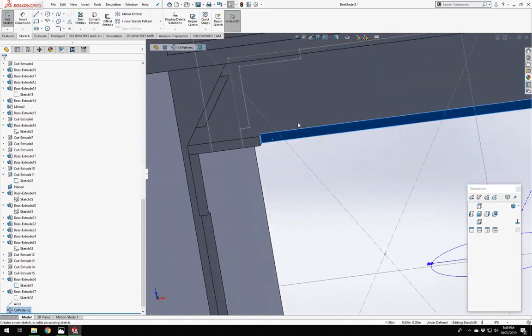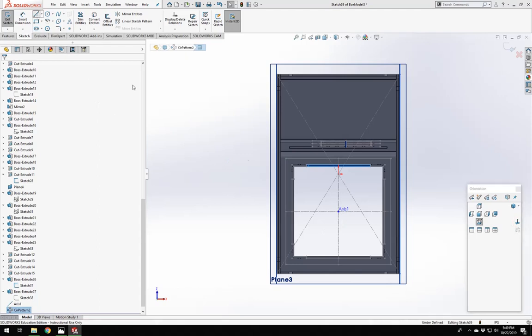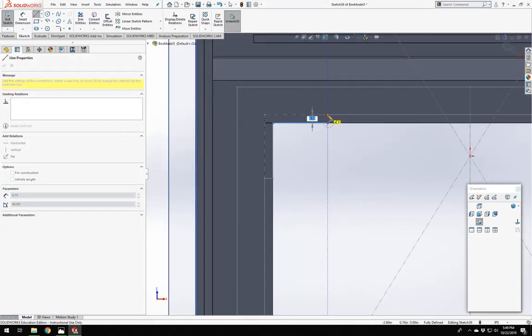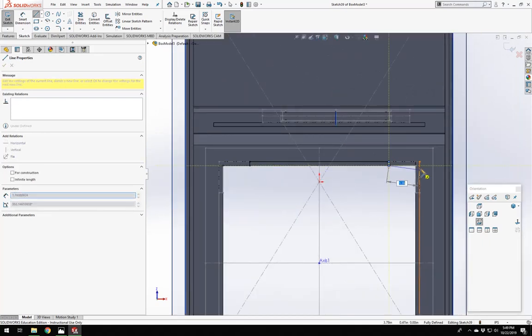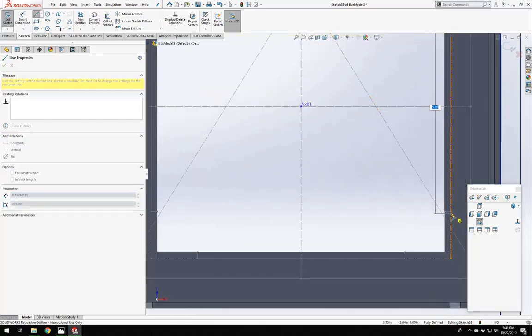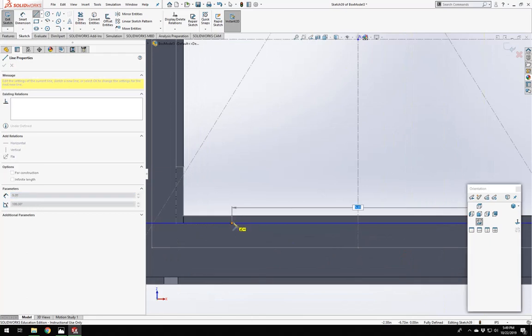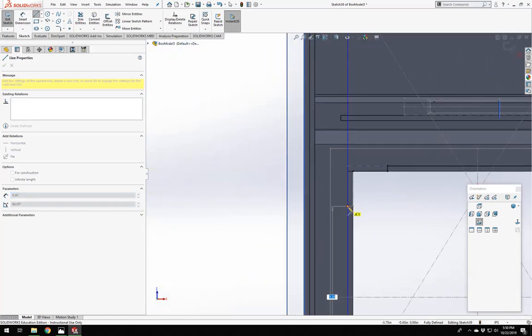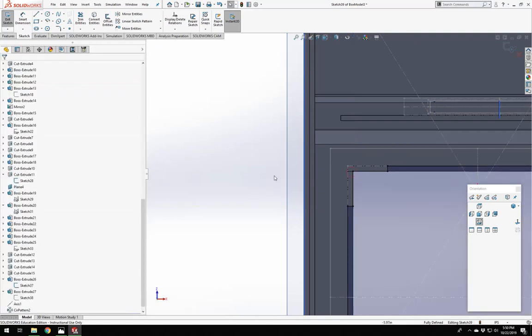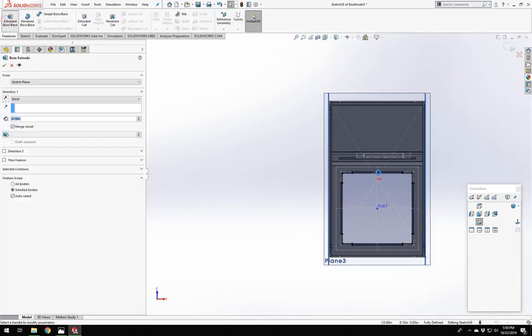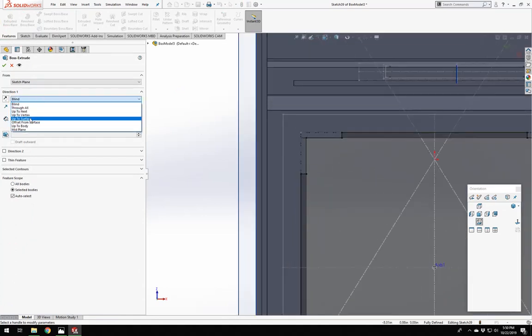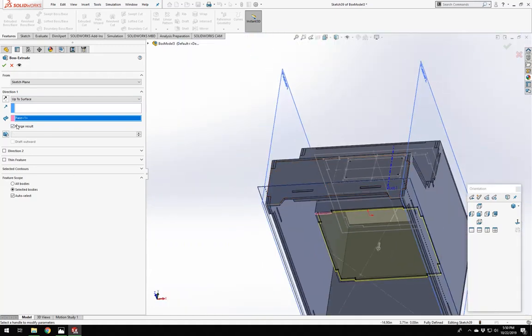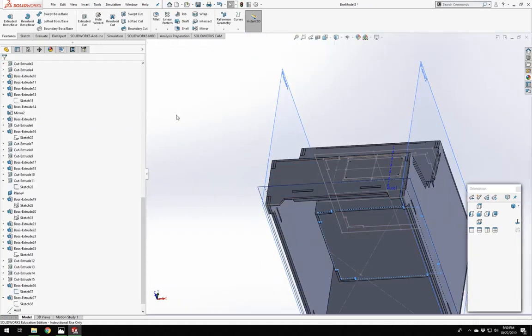So now all we have to do is select that face and just trace some lines. And because we're on the upper face of the piece, the material thickness is built in, so we can either extrude to the material thickness or we can just extrude up to a surface, which is what I think we'll end up doing here. There we go. So we can just say features extrude. We're just going to do up to a surface, which is going to be the bottom of one of these. Make sure we do not merge. And click that. Cool. So now we've got this bucket.